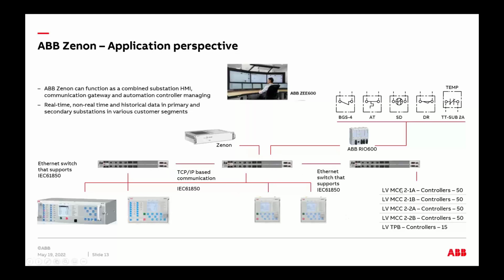At the same time, here I'm showing you another network, could be here a 480 level, right, low voltage. And I'm tying in also the MCC or maybe some low voltage breakers and so on, bringing that signal to another Ethernet switch, and then medium voltage, low voltage. Remember, I'm an HMI. I don't care about the voltage. I can be a player on both sides, and I pull that to the main power monitoring system, and then to my control room and so on. Maybe you also have some analog inputs that they want you to also monitor. In that case, you will have to use maybe a device that will change analog to digital inputs, and you just dump an RJ45 in the main hub of the Ethernet switches.